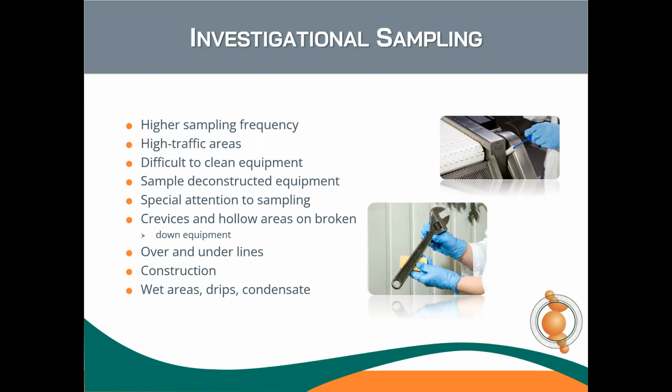The equipment should be deconstructed for sampling and deep cleaning, and it is essential to include perimeter zones and non-process areas in the sampling, since these areas can often be vectors for contamination due to traffic within your facility. The chart showing high-risk sampling sites is useful as a guide for starting your sampling.